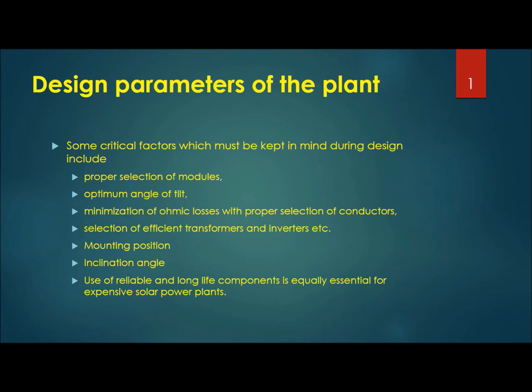So the actual energy output that one can expect from a given photovoltaic system depends on a large number of factors. Some of these are: the photovoltaic efficiency is affected to a greater or lesser extent by the temperature of the module, usually decreasing with increasing temperature. Nearly all module types show decreasing efficiency with low light intensity. The strength of this effect varies between module types.